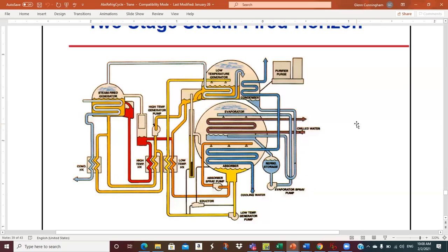And his research was on triple stage absorption. So if you think the two-stage cycle is bad, well, let's hang one more stage up there. And I have even heard of people that, I don't know if they've ever built one, but at least have done computer simulations on a 4-stage absorption cycle. So there's been lots of research done into this over the years.